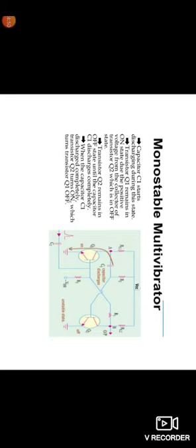Transistor Q1 is in on state due to the positive voltage from the collector of transistor Q2, which is in off state. Off state means it acts as an open circuit, so that VCC is connected to the capacitor. Capacitor C1 is already charged, so it discharges through the point A to the transistor Q1.